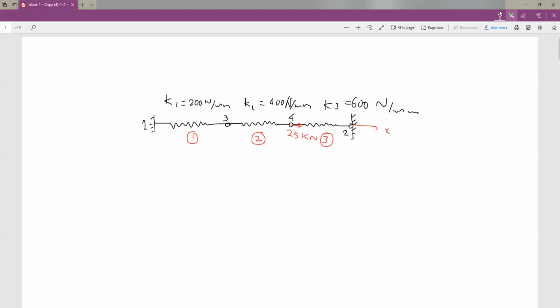So that is K13 for the first member. We will be writing, as per our formula, K, minus K, minus K, K. This was our formula, so in this form it was easy to write. Of course, you write the numbers here for easy view. We can write the stiffness coefficient, which is given as 200. So we can write it here: 200, minus 200, minus 200, 200.